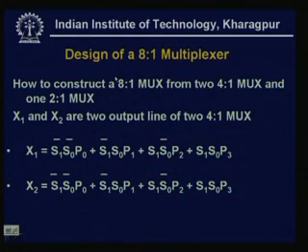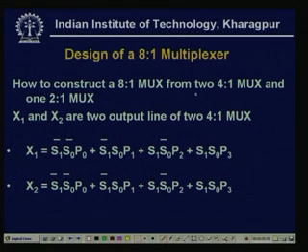Now, we consider an 8-to-1 multiplexer, and we see how 4-to-1 multiplexers can be used to design it. To design an 8-to-1 multiplexer, we need two 4-to-1 multiplexers and one 2-to-1 multiplexer.